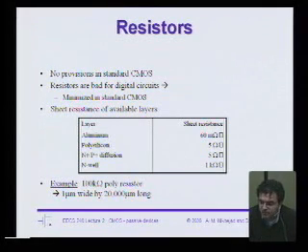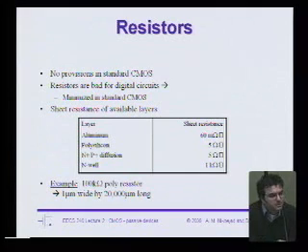It's not practical. Well, there are other layers available to us. There's the polysilicon itself. Polysilicon these days, if you look at a typical process, it's actually pretty low resistance. It's on the order of ohms per square, or 5 ohms per square. If you look back to like a 5 micron process or a 0.35 micron, that's like 50 ohms per square. So what's changed? Why is it the resistance is now lower? Lots of technology people here could give us the answer.